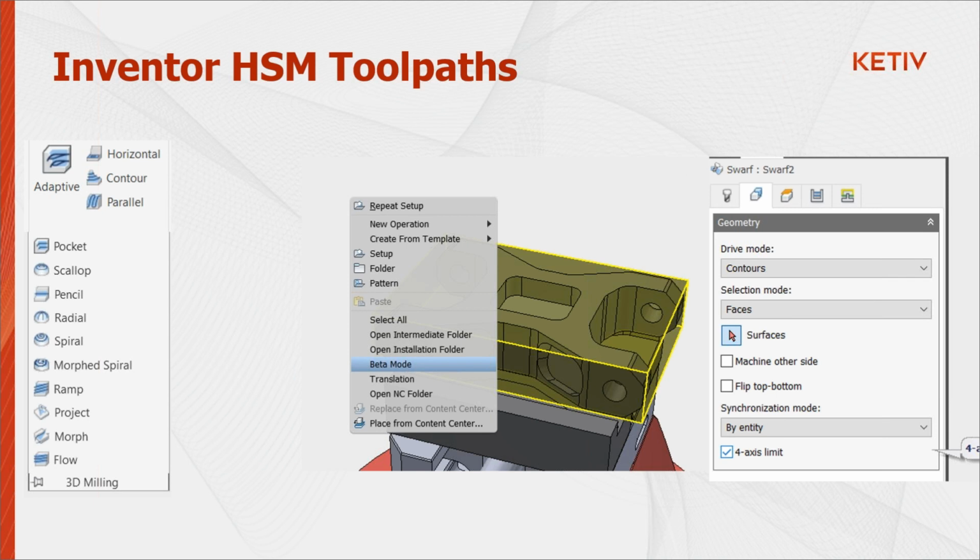What you also have the ability to do is turn on beta mode inside of Inventor HSM. Now, what beta mode does, it gives you some extra functionality. You guys do have to keep in mind, though, it is still being tested, right? So again, you want to make sure that you try this at your own risk. But one of the functionalities that beta mode brings to the table is, if you take a look at the swarf toolpath dialog box over here on the right, you have the option to essentially lock one of the axes, right? So instead of making it a true 5-axis toolpath, you can lock one of the axes. Now it makes it a 4th-axis toolpath, and now you can use it, for instance, on some sort of rotary table or something of that sort.